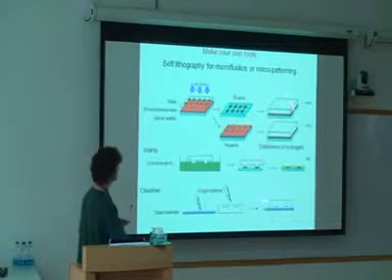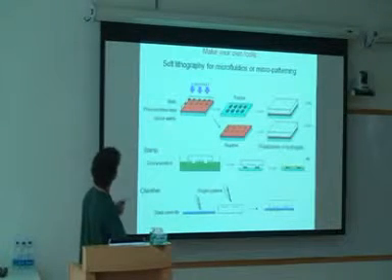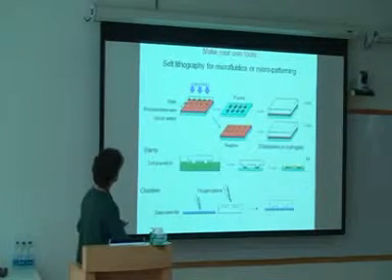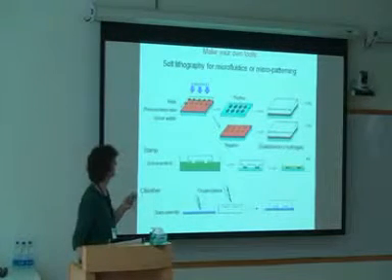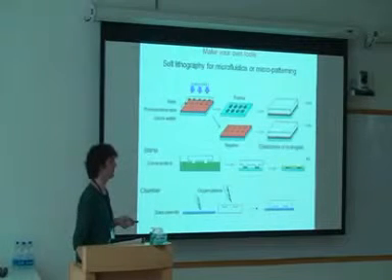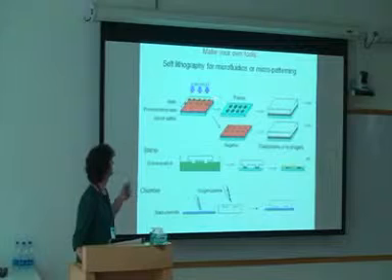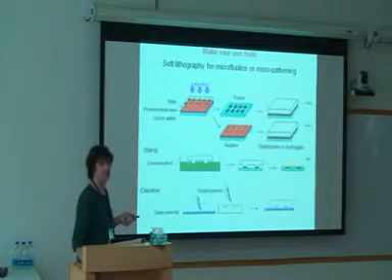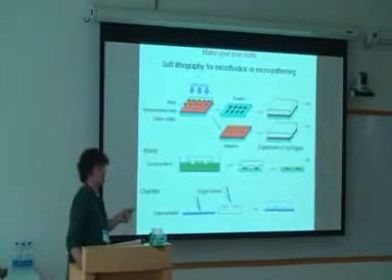Or you can also use them to make chambers or wells or this kind of thing. But at the end, it's always that. So it's this sort of photolithography which has been developed for microelectronics and which was transferred for biology. I must say, really, the people who popularized that is the lab of George Whitesides of Harvard University, and they call this kind of technique soft lithography, using materials like PDMS, which are biocompatible.